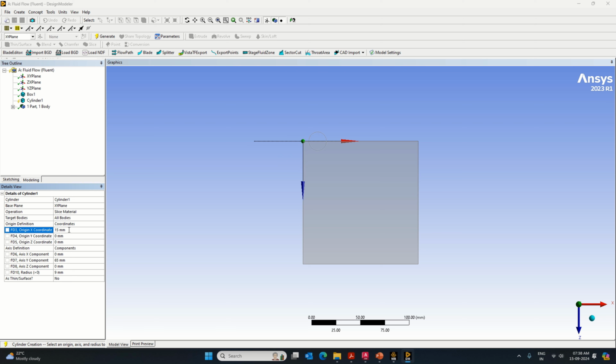So first the portion. Now the next is the distance between the two cells, which is 23 vertical distance. So let's take it 23. One more time, let's create a primitive, that is cylinder. Instead of add metal, make it slice metal. So the radius is by default 9. Y component I will make it 65. Let's make z equal to 0. The x component, earlier we had 15, so this is also 15. Only the z component will be 28.5 plus 23. So let's see, 28.5 plus 23, that is in the vertical direction.